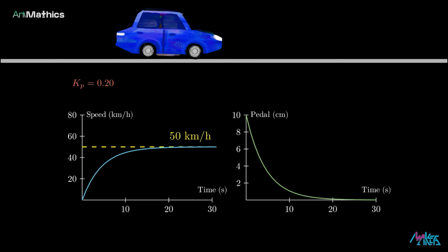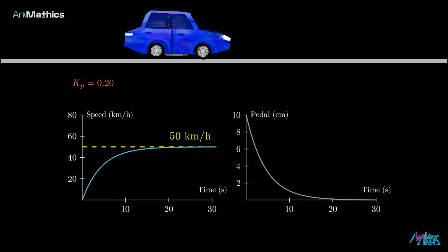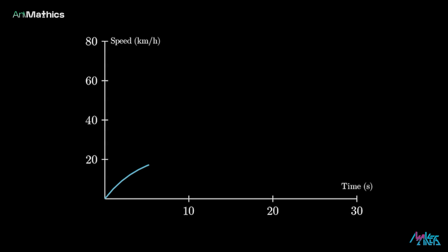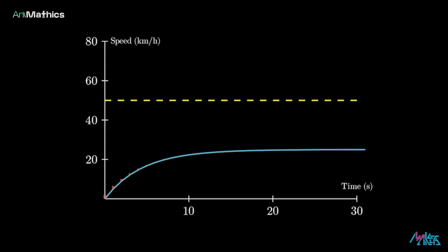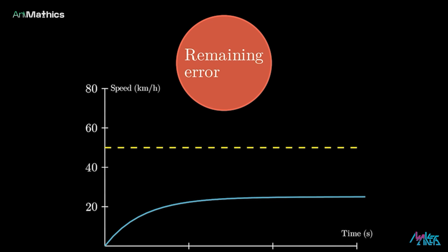And from that, he realized that to steer a ship, or just about any kind of automatic steering system, simply knowing the proportional deviation was not enough. We need more advanced calculations to overcome the limitations of using only the proportional term. Looking back at the problem, we need a mechanism that adds up the remaining error over time. Even if each individual error is small, if it keeps lingering, the system needs to respond more strongly.